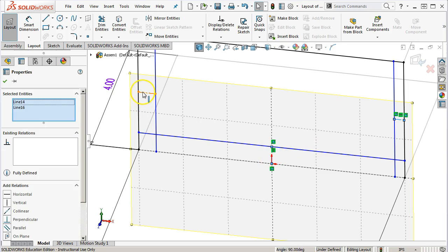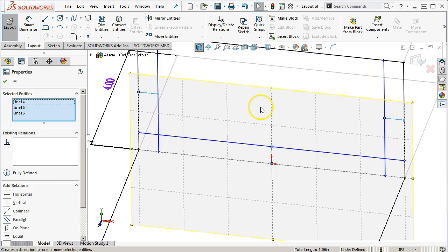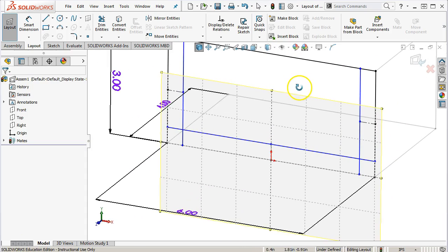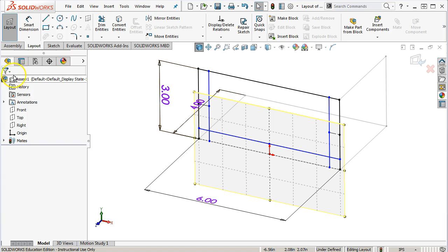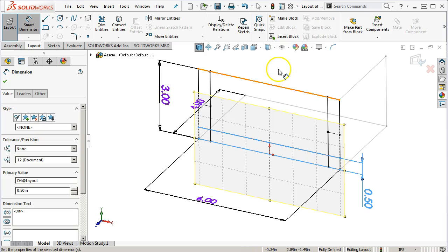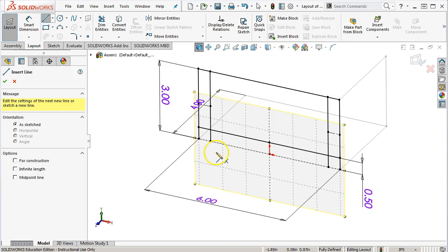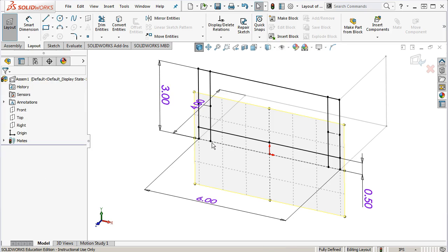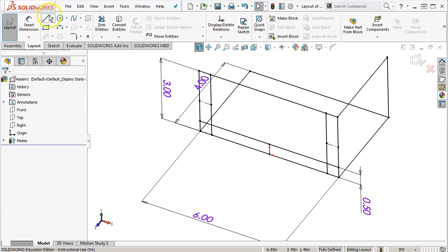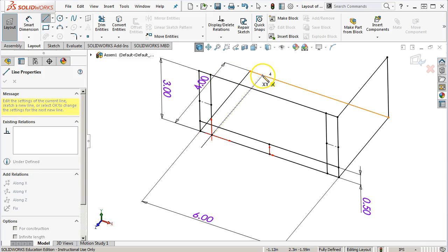Yes. There's nothing in the model tree there that shows. I don't see a sketch or a feature. Nope. We're inside of the layout. All you get is kind of that little parallelogram in the upper left, and my confirmation corner. That's your only indication that you are sketching at this point, or where you're sketching or what you're sketching with. So let's make that the 1/2 inch. That drives the sides, and so I need to get out of my front plane. I'm going to drive one back.